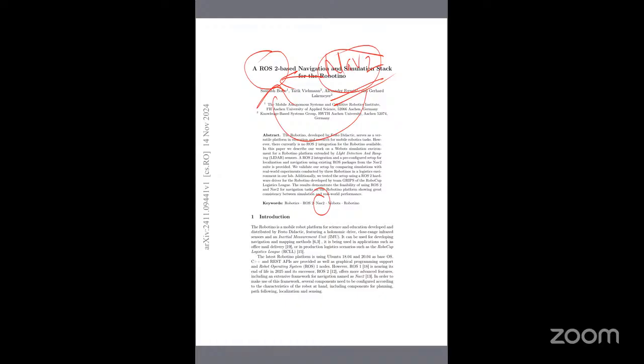As I have mentioned, the first one is localization. Localization means the robot doesn't know where the correct location is, but using this navigation package, localization is possible. The second one is mapping. Mapping will create the entire map of the entire home. The third one is path planning. It will find the shortest path from, say, point A to point B. That is what is called path planning. And the next one is obstacle avoidance.